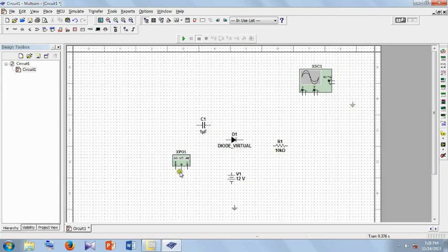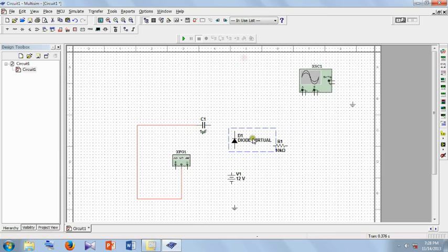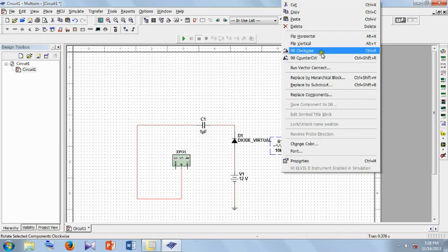So we have to connect the circuits using wires. See, this is for connecting the circuits. Here I will be rotating counterclockwise because I have to give the negative part of the diode to capacitor N, and the positive part of the diode to the positive of the V reference and negative part to ground. You can see negative part to ground, and rotate it clockwise.